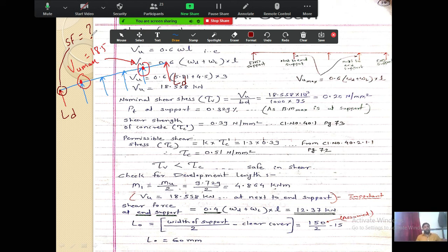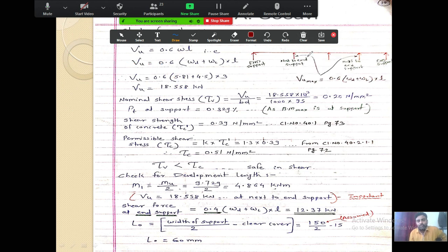So we have already seen in table number 13 the dead load and live load coefficients for the shear force at this point. And if I am not wrong, then the dead load coefficient may be something around 0.4 and live load coefficient was 0.45, I think, something in this range. We will see right now. Here also, no, both are 0.4. Okay, both are 0.4. Here it is, both are taken as 0.4. So I will not go to the IS code now. So we know this already.